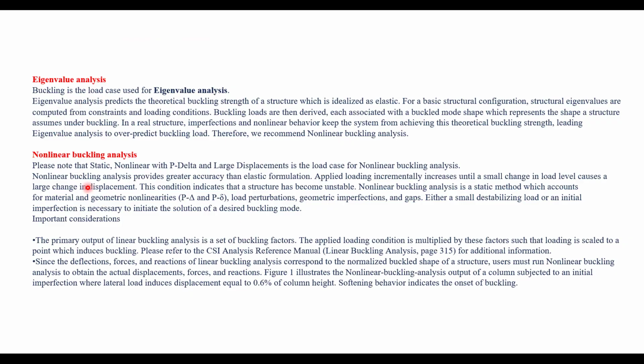This is about the explanation: what the eigenvalues are, how we extract the mode shapes from them, and what we do in nonlinear buckling. For information, the linear buckling we are going to do is not related to the material properties, and it is just a scale. Whatever you extract from the buckling analysis is a mode shape, and you get the buckling load factor for that particular component, which is not 100% accurate. It is here and there. We can consider 35 to 20% slightly near to the non-linear buckling analysis.